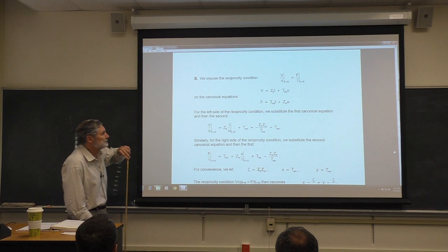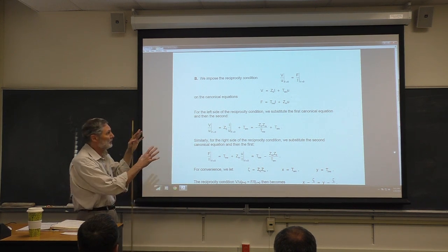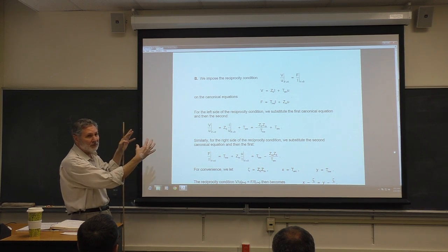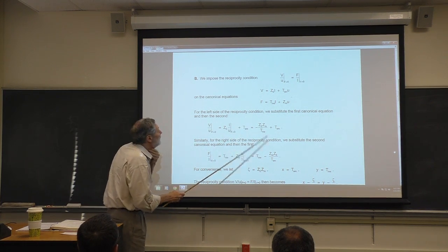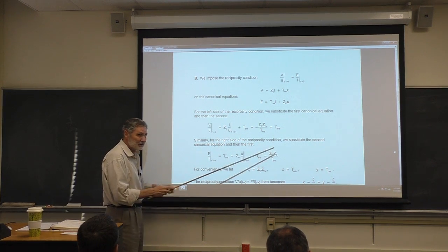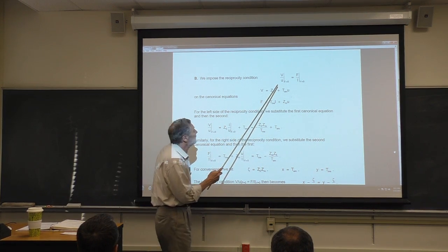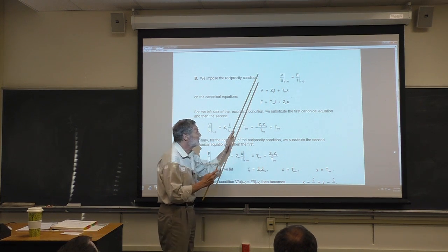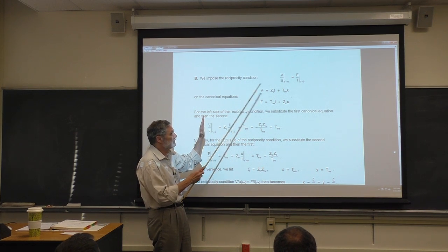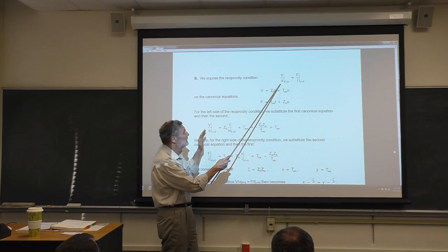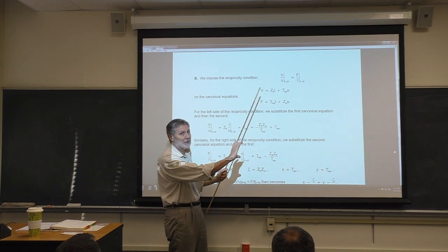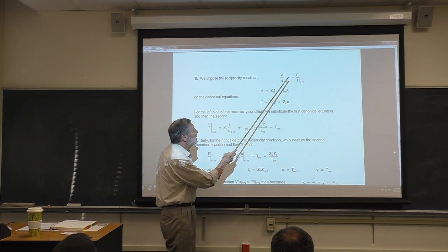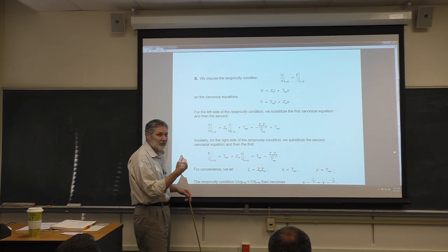You remember, we looked at the schematic representation of a transducer, a double port transducer. And what reciprocity means there is, again, the transfer impedance is symmetric. So we look at the left side, the electrical side, thinking of that as the drive, we look at the voltage divided by the response, which is now the velocity, and we have to short that terminal there. So that's what that means. That has to equal the transfer impedance going the other way.